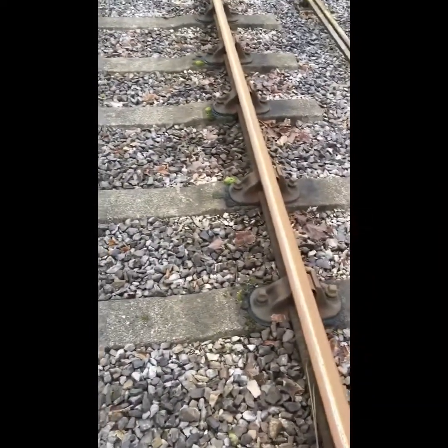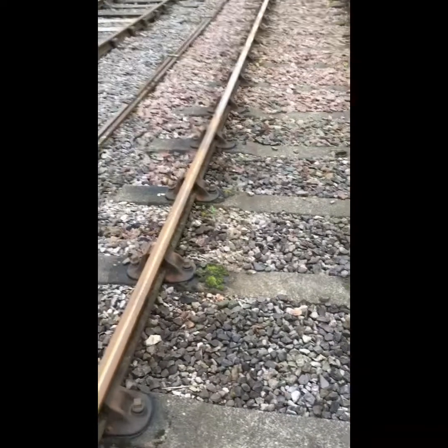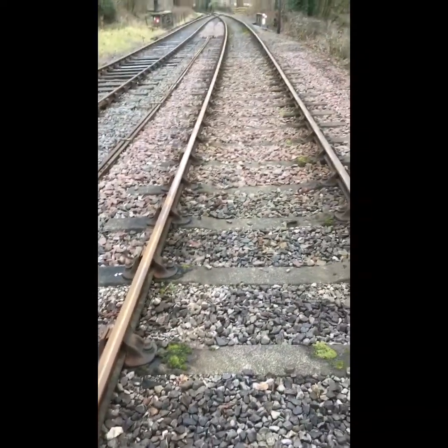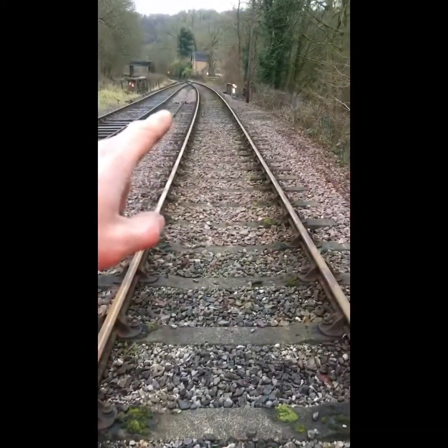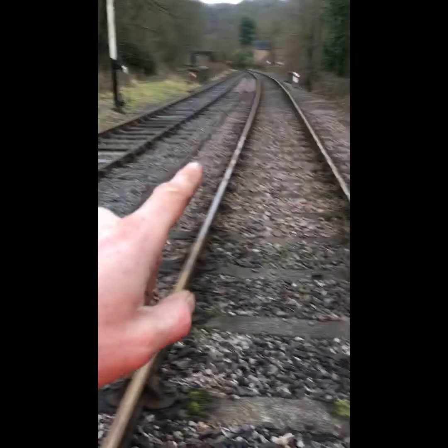So this is good ballast here, but what you don't want is saturated ballast with a ton of muck in it and chemicals such as from factories, because that will alter your ballast resistance and alter the voltages that you energise and de-energise the tracks at. Also, you want good drainage. So here we're on a steep banking, which is quite good.